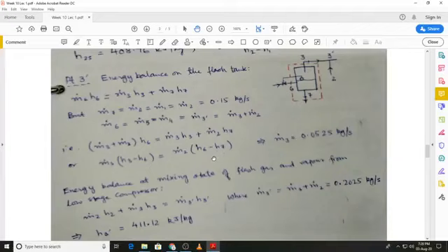The enthalpies h3, h6, h7 etc. we can then find out, because we know h3, we know h6, and then m dot 3 comes out to be 0.0525 kilograms per second. Remember, h3 is equal to hg at the intermediate pressure of, I think, 0.45 megapascal.